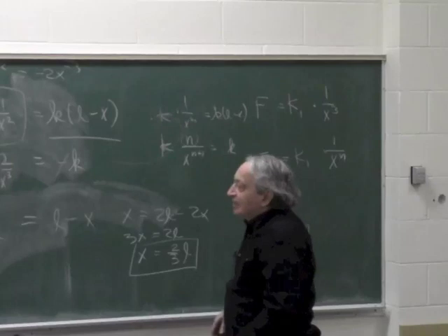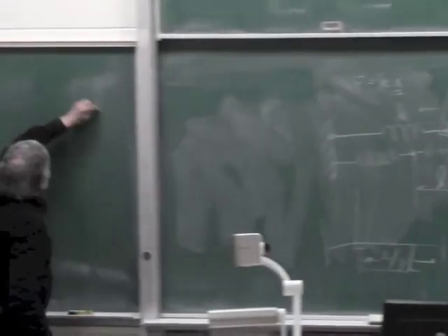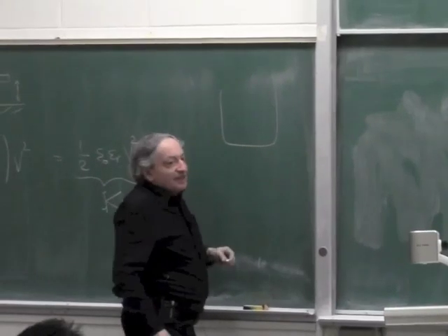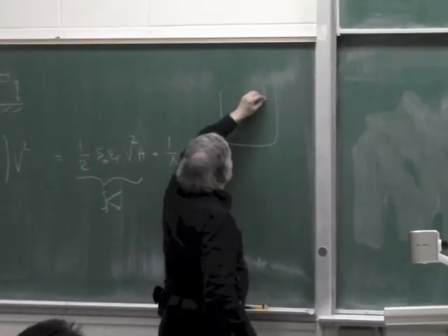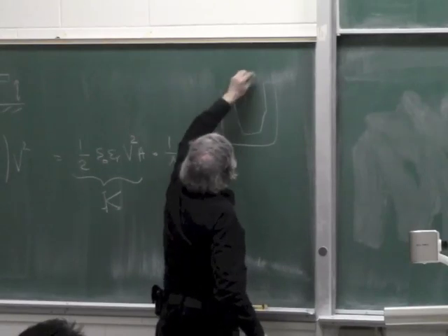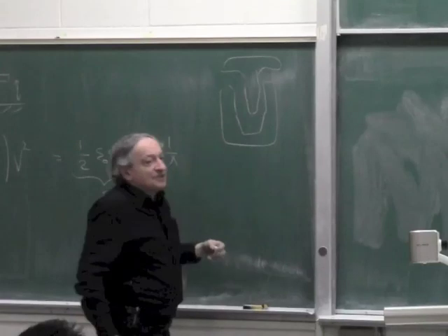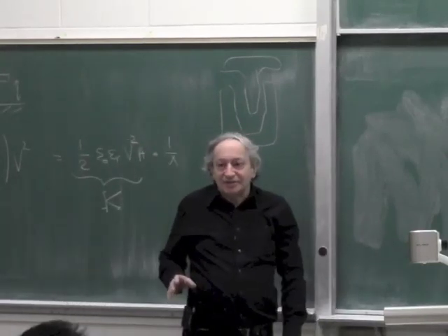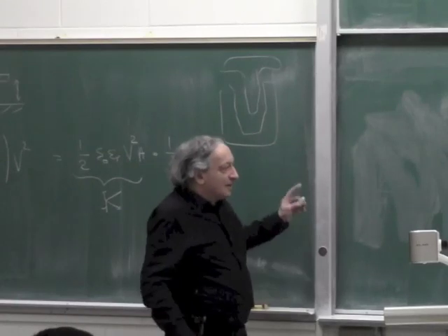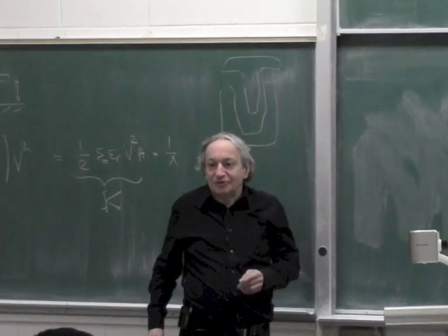For example, when you design a solenoid, a lot of times you design it not to be square law. So you design it with a special shape inside, something like this. You design it with some shape to try to linearize it a bit. And when you do that, you can get any n, which doesn't have to be an integer. Okay? I'll show you in a minute another example of a solenoid where n is 1.5, not 2.